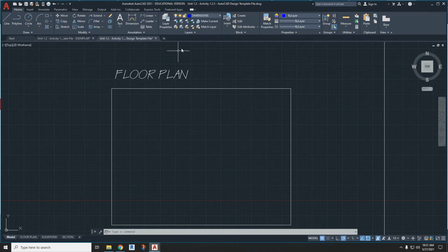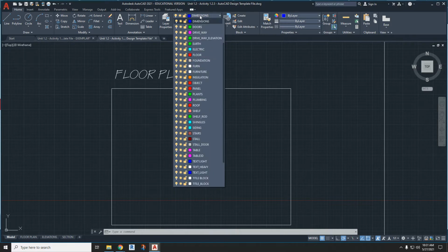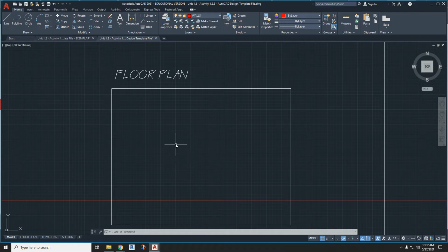All right, so to draw the floor plan, you need to start with drawing walls. And so I would suggest you switch to the wall layer. Scroll down to see wall layer right there. And you can do individual lines or you can do a rectangle. Since our shed is a very simple rectangle, I would just do that. Start here and then click and then drag over, and then you type in the dimensions. First one you see is the bottom, so it's the length.